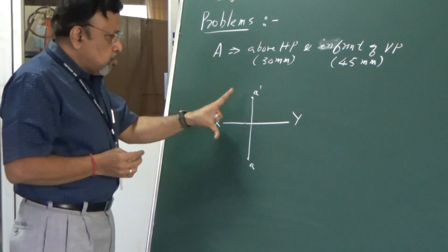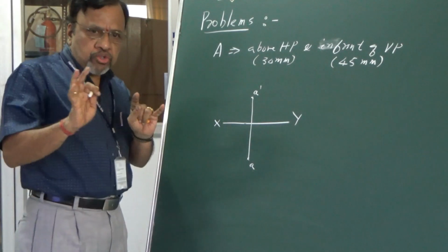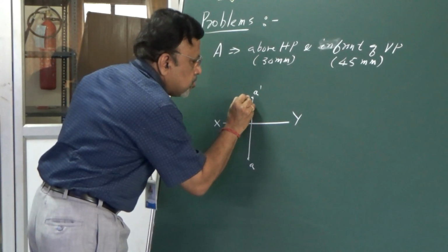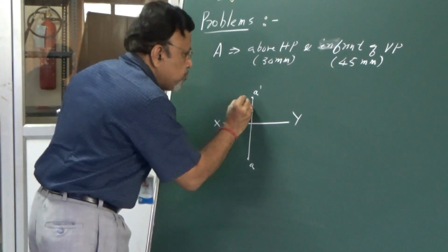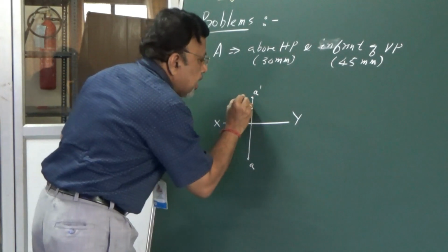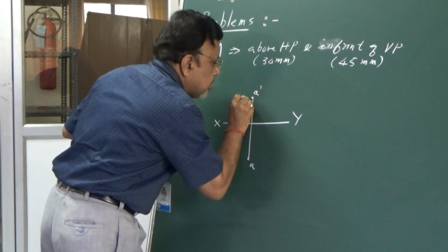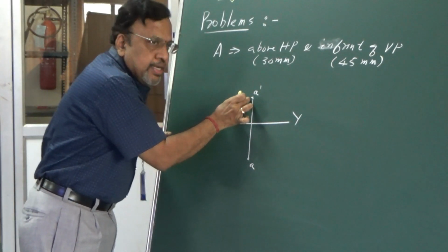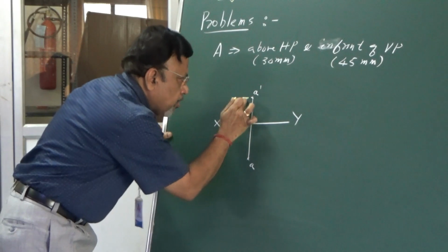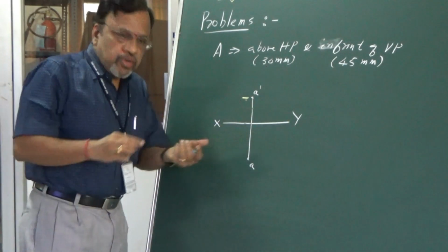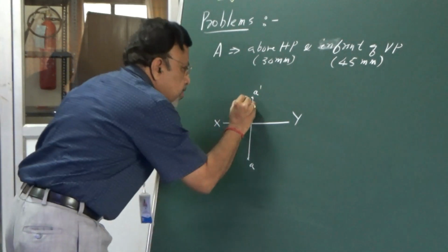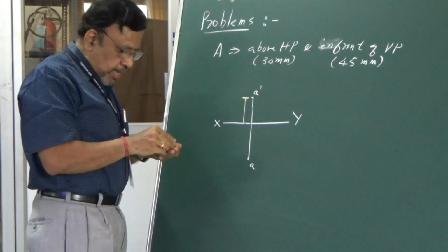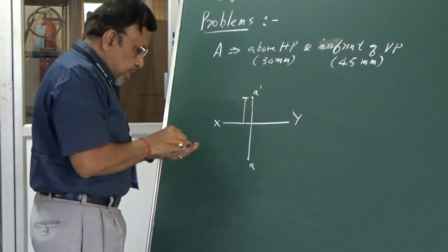So what you do is, especially to show the dimensions, you just follow this convention. Let us say from point A I will take some 5 mm distance. Then I will just draw a line equal to 10 mm distance. That is, you leave 5 mm, then take 10 mm. Similarly, the point is, I want to measure from XY line. Now what you do then, I will just simply draw this another light line. Then at the middle, I will show the distance.